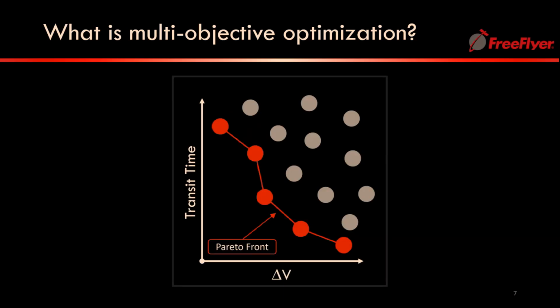And then at the end of that transfer, again, we're going to end up with 2 objectives, and we want to minimize those objectives. And the goal of multi-objective optimization is to come up with a set of trade-off solutions, in technical terms called a Pareto front. So the Pareto front is the set of trade-offs that you as the engineer can choose, the set of optimal trade-offs.